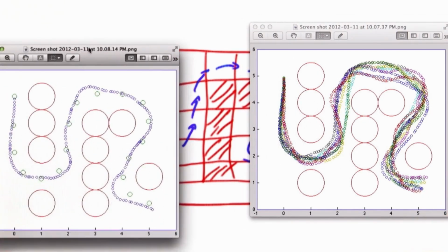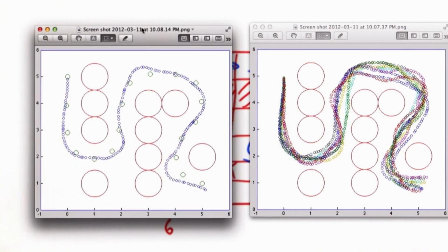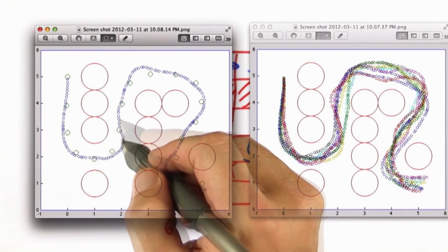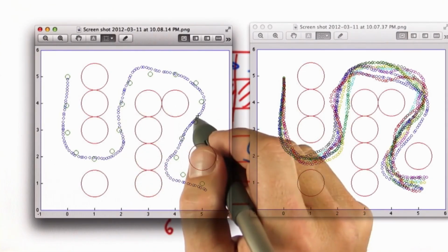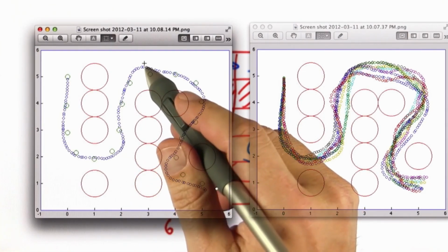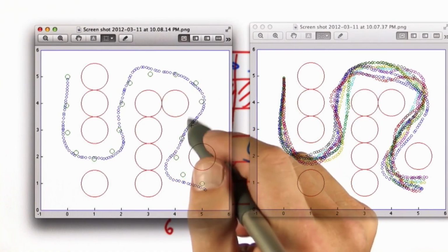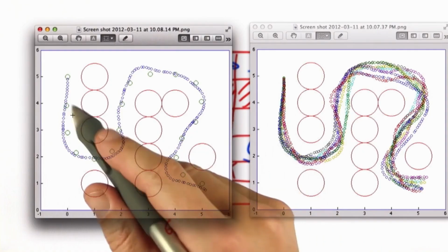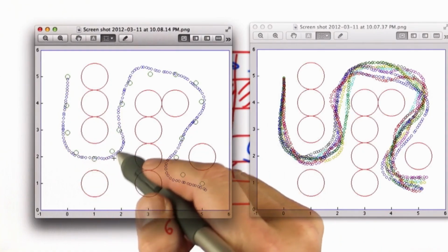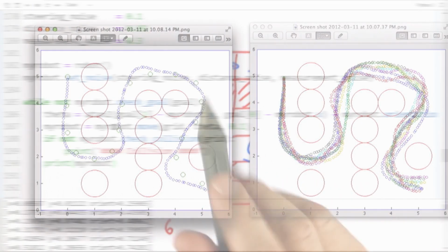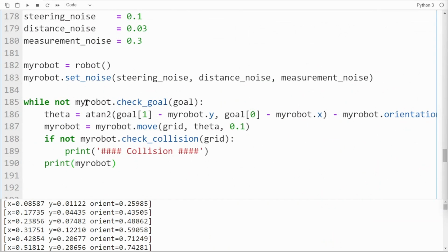If you look at them in detail, like this solution over here, you'll find that the spacing of the circles is somewhat variable. You'll find that there's little corners over here that are either the result of control noise or of measurement noise or of my somewhat deficient implementation. And you also find the control set points that are the smooth points of my A-star planner, as shown here in green. In the version that I implemented for you, the controller does something very, very different.